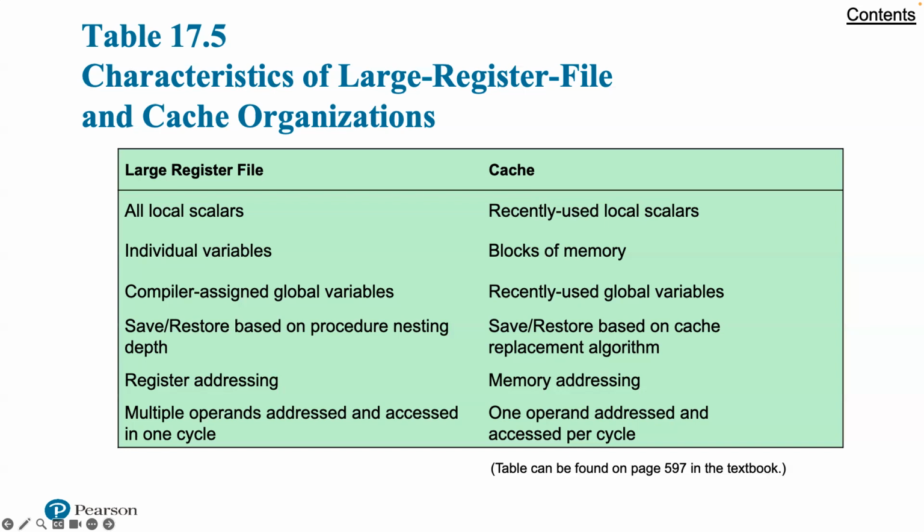On the other hand, the cache may make more efficient use of space because it is reacting to the situation dynamically. Furthermore, caches generally treat all memory references alike, including instructions and other types of data. Thus, savings in these other areas are possible with a cache and not a register file. A register file may make inefficient use of space because not all procedures will need the full window space allotted to them. On the other hand, the cache suffers from another sort of inefficiency.